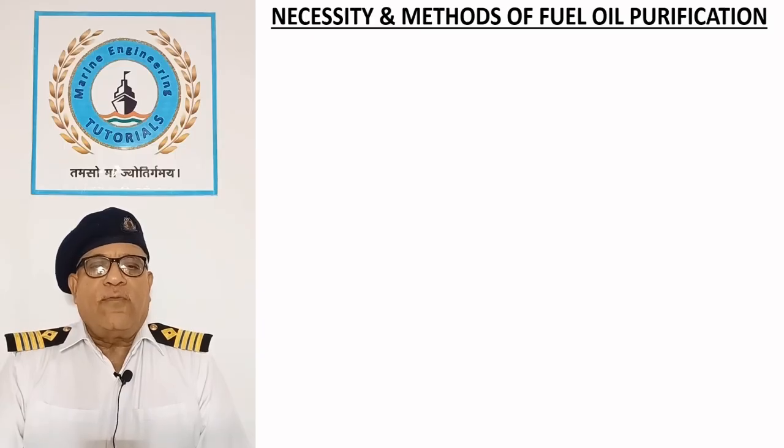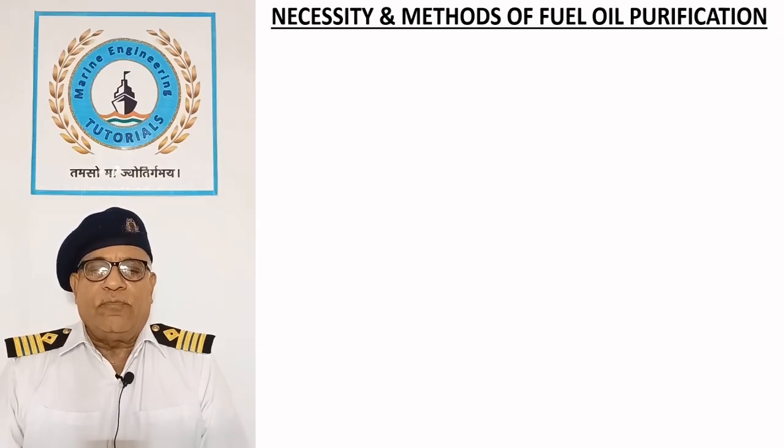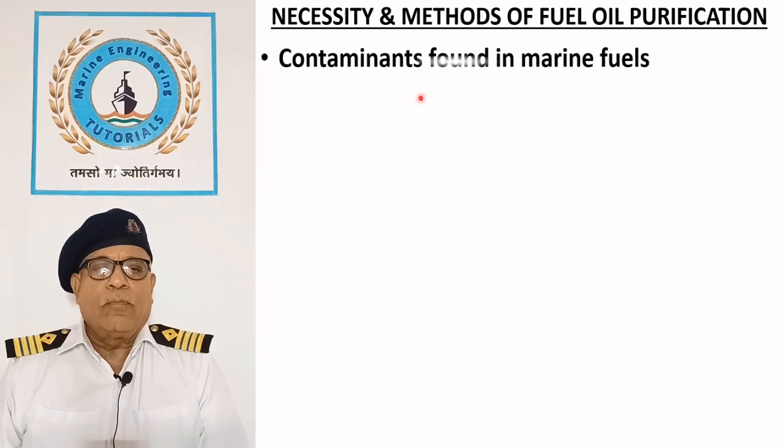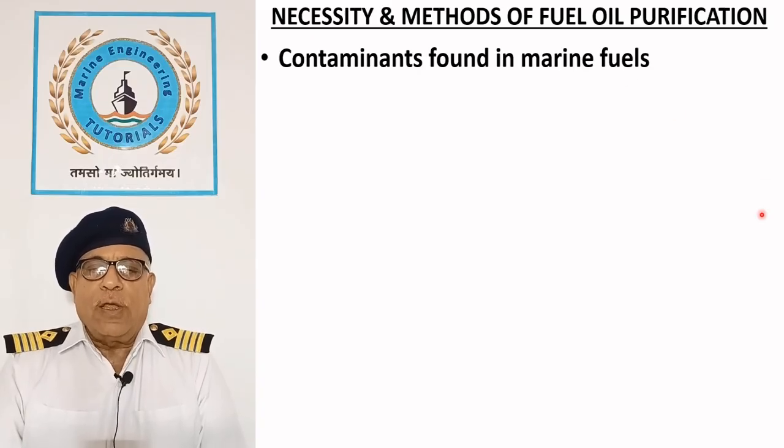Necessity and methods of fuel oil purification. Fuel oils need purification before use in marine diesel engines to ensure efficient engine performance, reliability, and longevity. Contaminants found in marine fuels. Marine fuels may contain water, sludge, and catalytic fines, which have several harmful effects on engine performance, reliability, and lifespan.